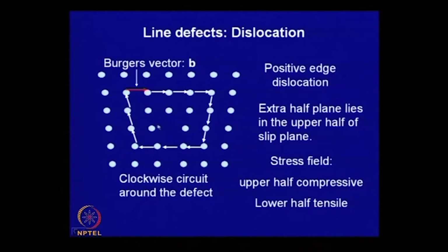In reality this stress will not be 0. You have to move this dislocation, which has a surrounding stress field, and this stress field will interact with the periodic stress field existing within the crystal. So, to move this stress field within a periodic stress field, you will need to overcome a small amount of lattice friction stress, and this stress is much smaller than the ideal strength of the crystal.